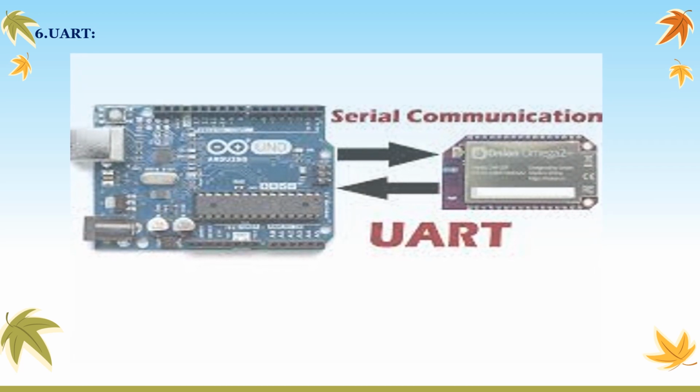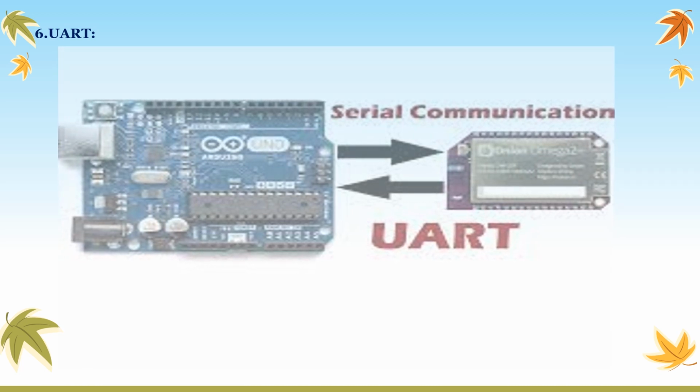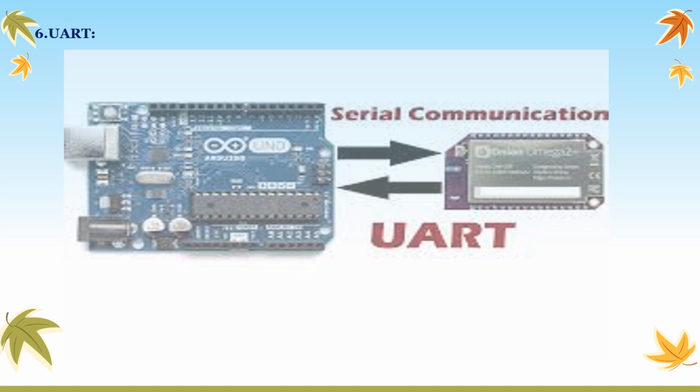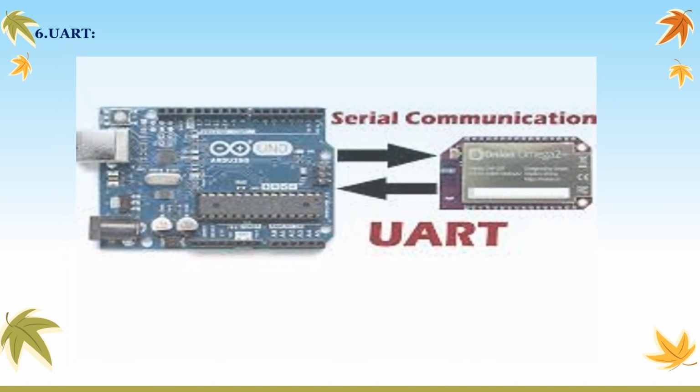In UART serial communication, the data is transmitted asynchronously, i.e. there is no clock or other timing signal involved between the sender and receiver. Instead of a clock signal, UART uses special bits called start and stop bits.